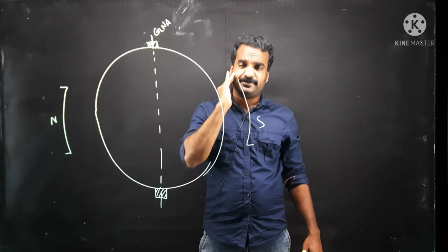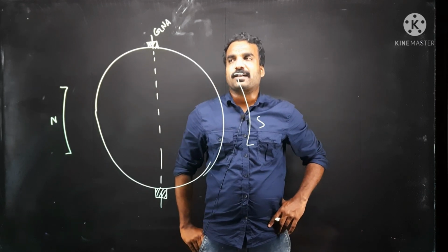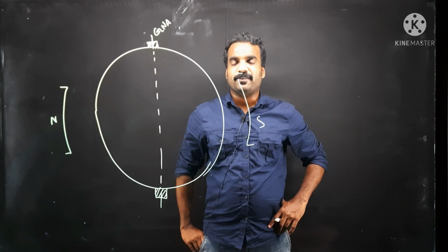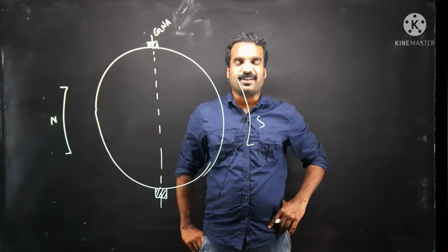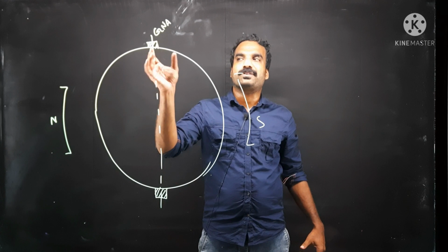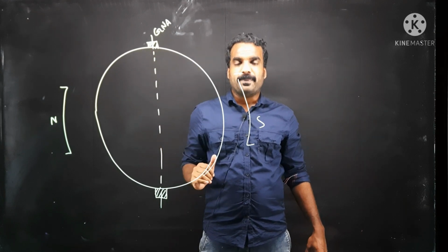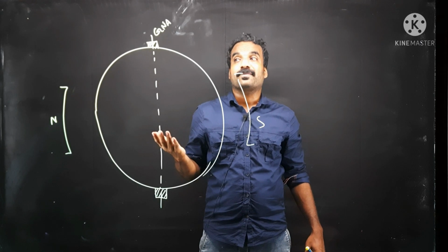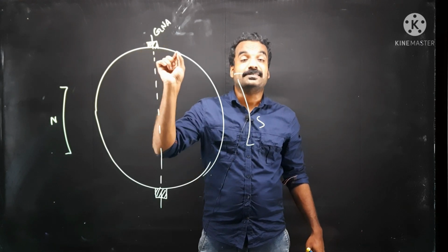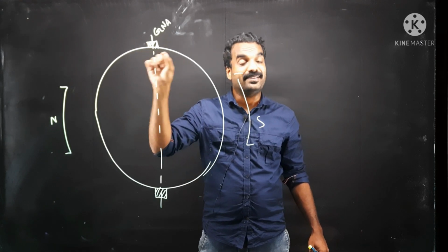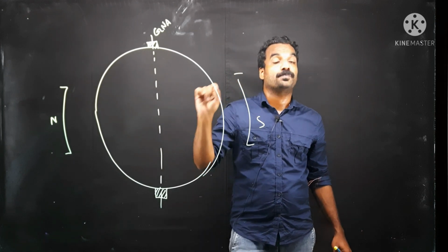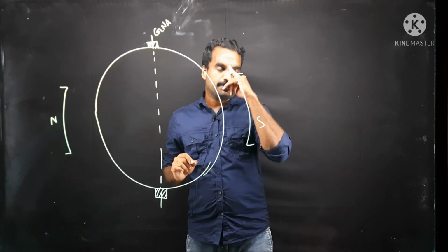Why? Because when armature flux appears, we get a new resultant flux, and then we have to shift the brush to the new MNA, the magnetically neutral axis. Otherwise, the brushes are situated on a magnetic area. This will cause sparking. You have to write that.